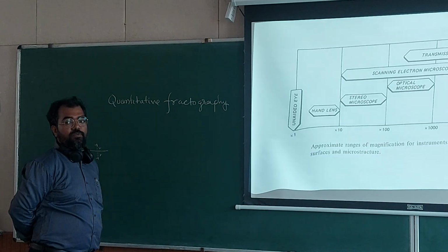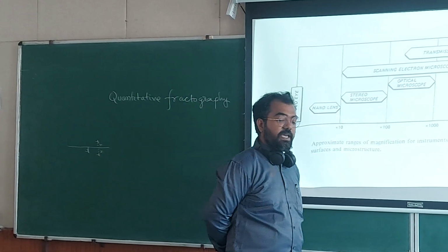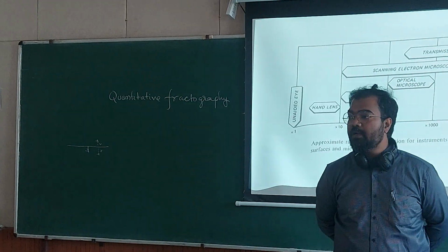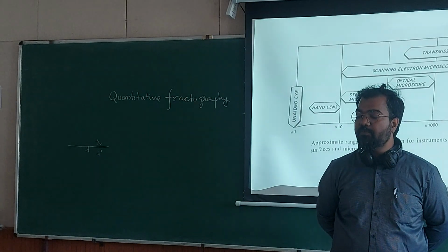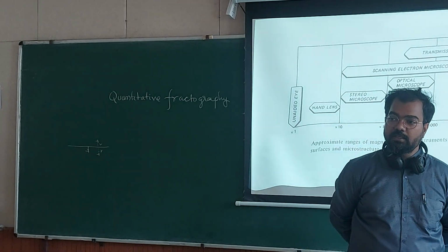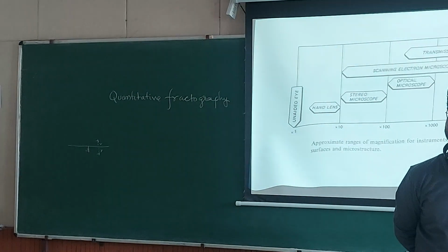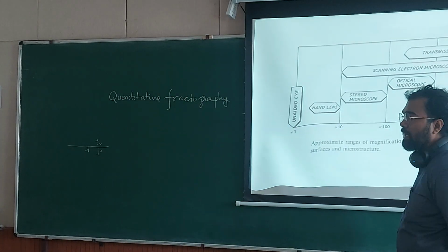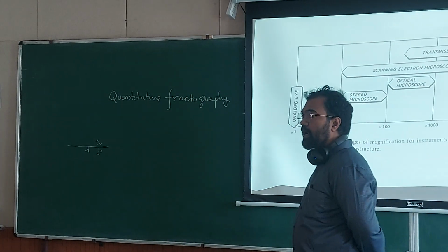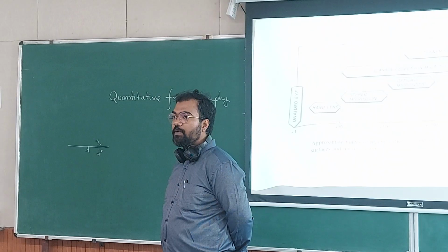So whatever we do with the K1C, J1C and parameters like that, they will tell before using the component that this material you should use, and this should be the dimension of the material based on the design parameters. Fractography is something which is post-mortem of the material.